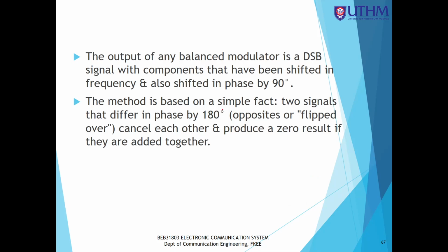The method is based on the simple fact that two signals that differ in phase by 180 degrees, opposite or flipped over, will cancel each other and produce zero when they are added together. So this is the phasing method.